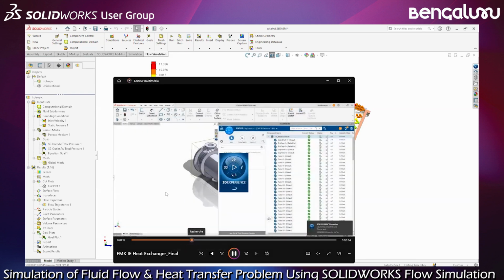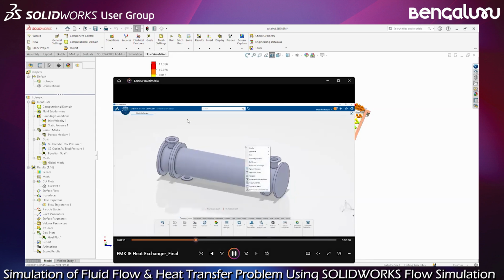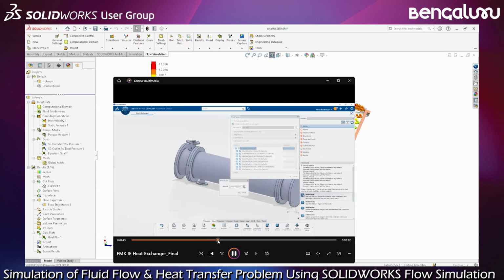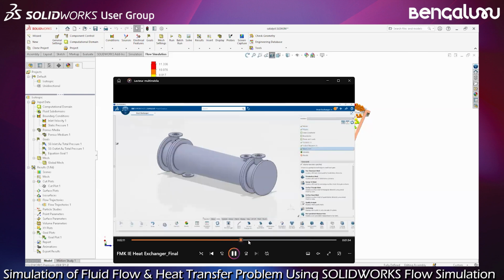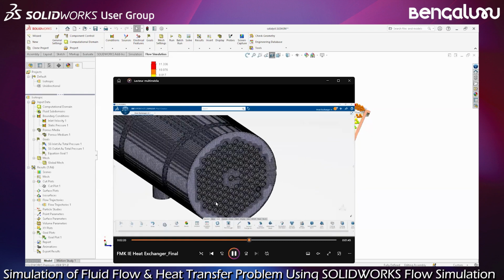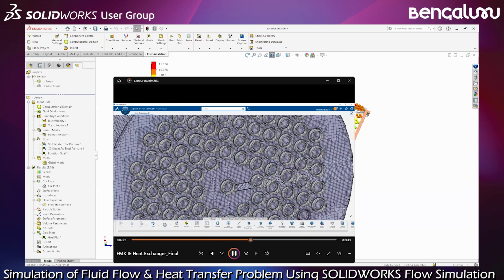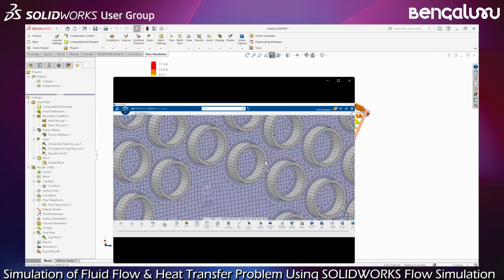Then you are in SolidWorks, you switch to the platform, you retrieve your geometry, and you define your settings through this interface. I try to go faster. Once you run it, this example has maybe 15 million cells. It uses a body-fitted, hexa-dominant mesh.